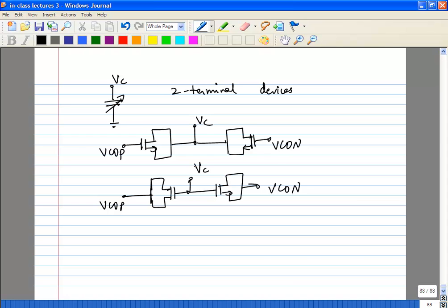Okay, obviously the first thing is in one case you may have a curve like that, in the other case you may have a curve like this for the frequency versus control voltage, but that's not a big problem at all. You can just change the feedback sign of the PLL into which the VCO is locked, so that's not a problem. Okay, so what other problems can you think of? Okay, what kind of loading? Why should there be a DC loading?